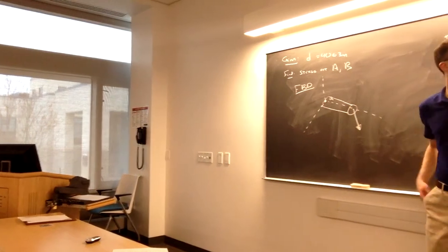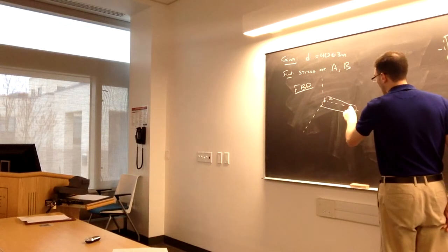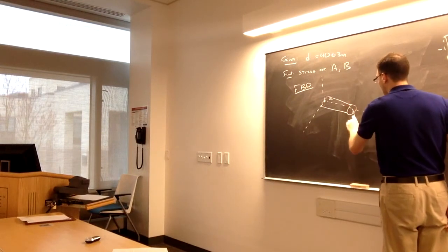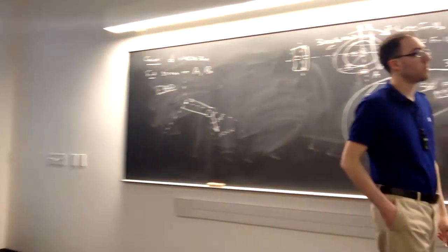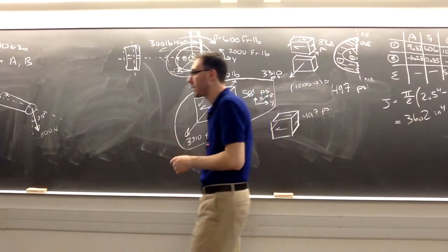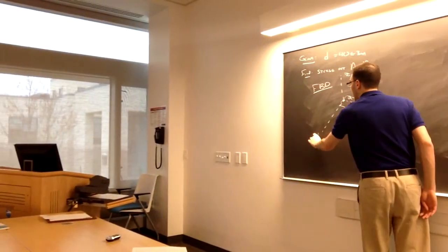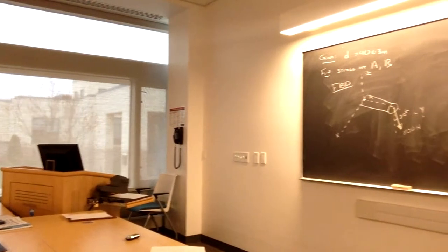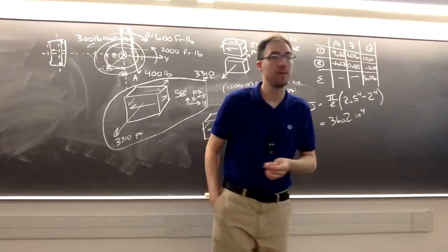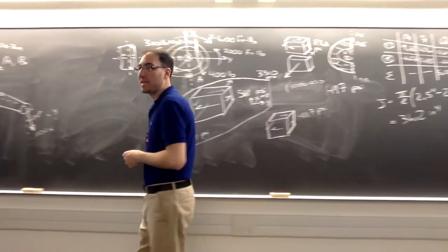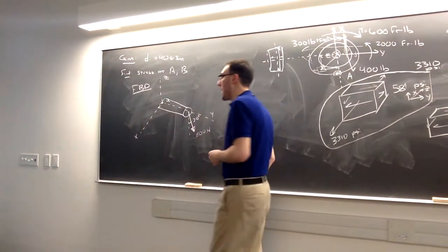I have that external force of 800 newtons. That is 30 degrees from the vertical, which is the z-axis, or the negative z-axis in this case. We call this z, y, and x. And that 800 newton is in the zy plane. Where I made that cut at Q, I'm now going to have my 6 internal loads that are now exposed.